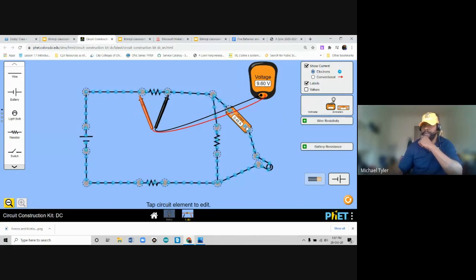Okay. For an ammeter, you have to connect it in line with the circuit. That's the most important thing. For a voltmeter, you can test each potential difference at each resistor or load. All right, so this is in essence all you need.